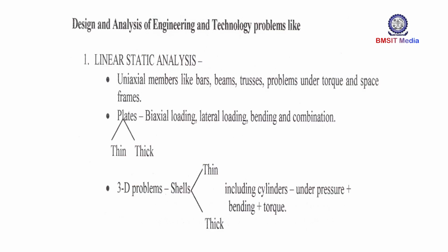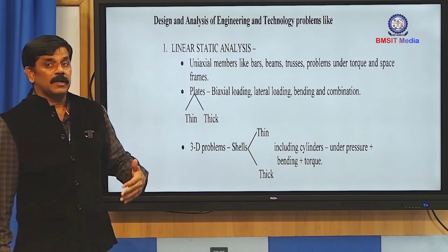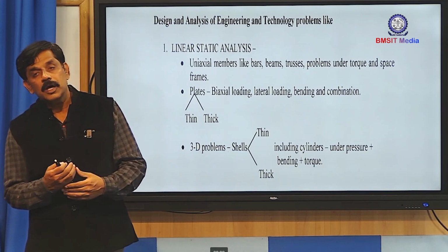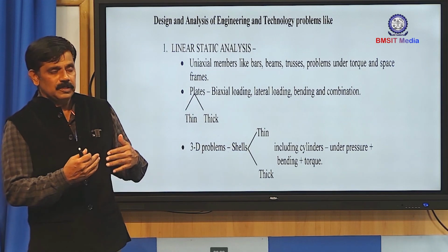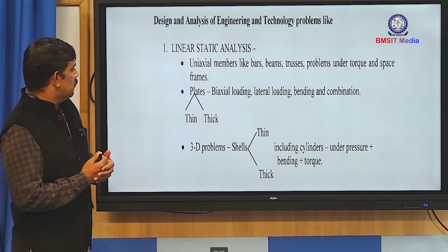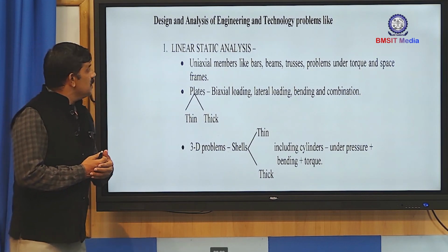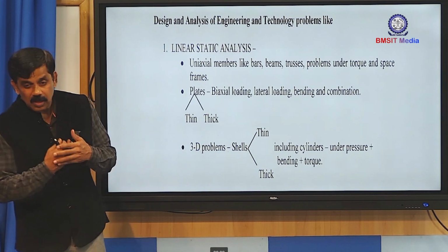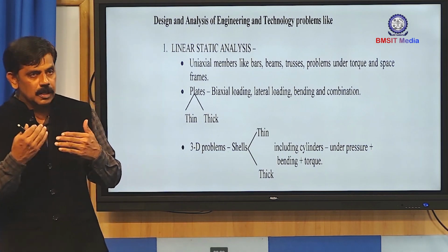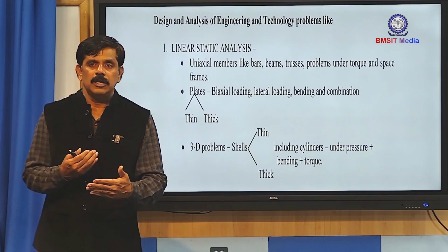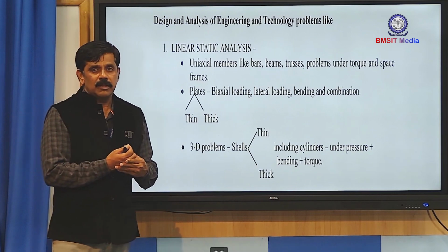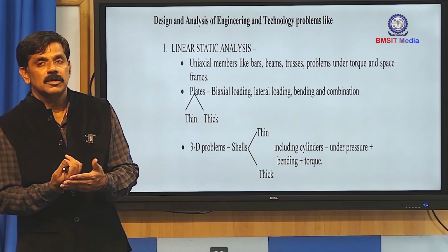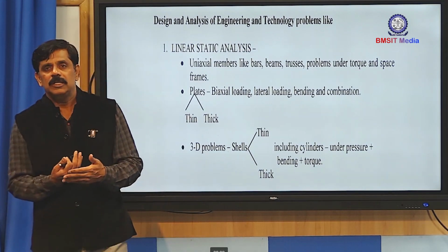Then, where exactly are the different applications of finite element analysis? We have given some photos which show the applications of finite element analysis. But if we broadly classify them, it can be used for linear static analysis. Once you say static analysis, we are assuming that the load on the component or system is constant with respect to time. When you come to dynamic analysis, the best examples are an earthquake, moving vehicles or moving aircraft, where the loading changes with respect to time.